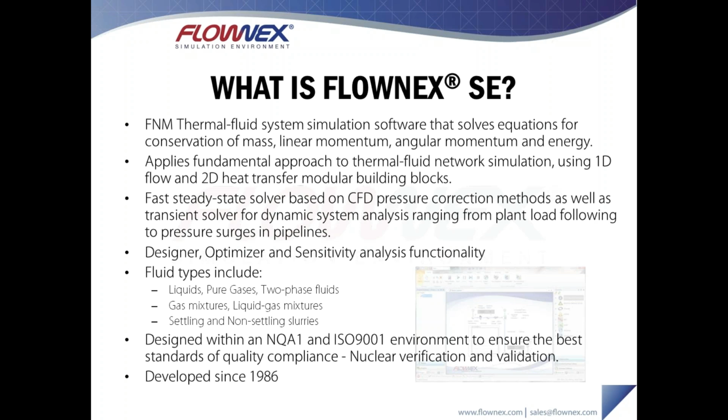The software itself is able to do simulations in both steady state and in transient, and includes many different types of fluid models. So we have fluid models for liquids and gases in the sense of compressible and incompressible models, as well as more complex models like two-phase fluid models or mixture models for gases or liquid and gases if you're looking at perhaps modeling combustion. And then also some further models for slurries, for both settling and non-settling slurries, taking into account shear rate dependent viscosities.